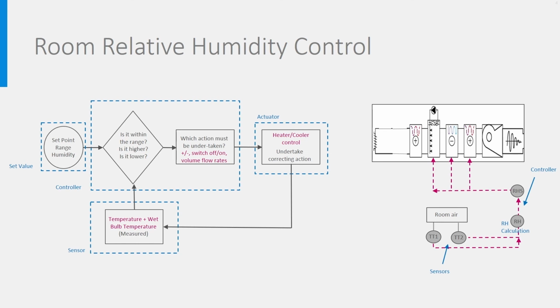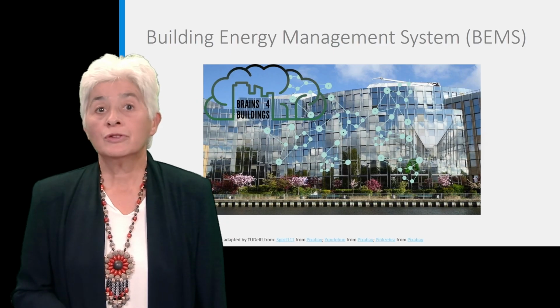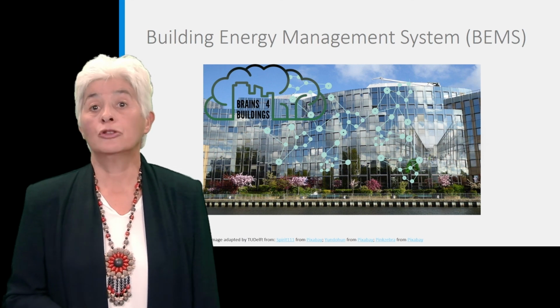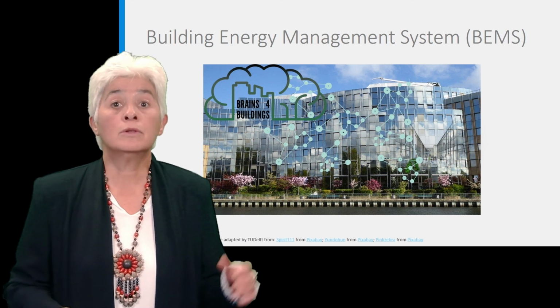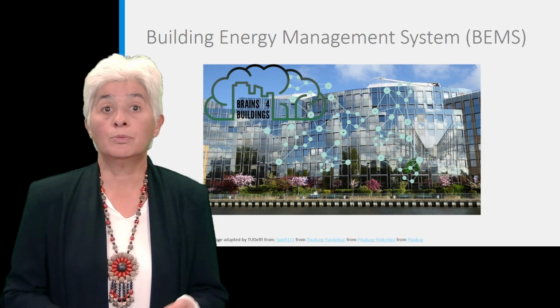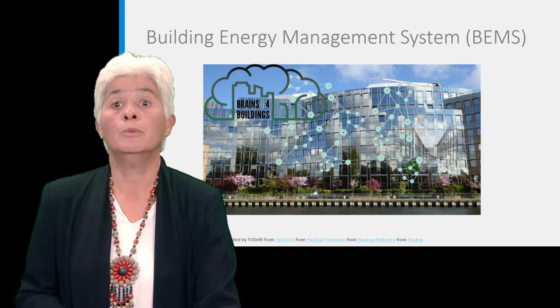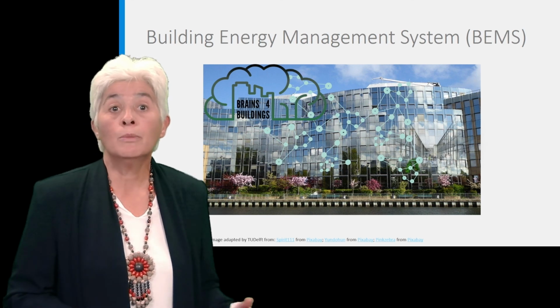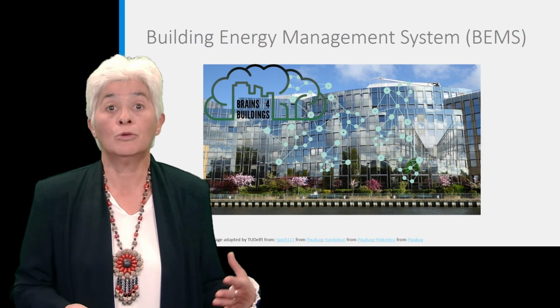For these two parts, temperature control, as described in previous slides, is needed. So, there are control loops asking other control loops to come into action. Each air handling unit has its own controls. The room control communicates with them through an interface. You now probably understand why automated building energy management systems are needed, especially in large buildings. There are sometimes hundreds of controls developed either by the producers of components like heat pumps, boilers and valves, or by the HVAC control engineers. It all must fit together, and that is quite a thorough job.